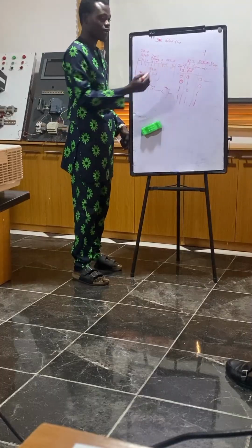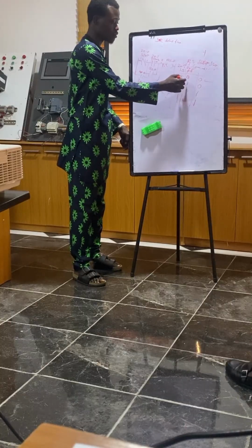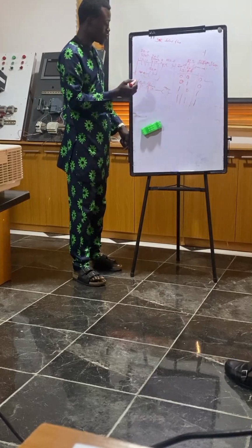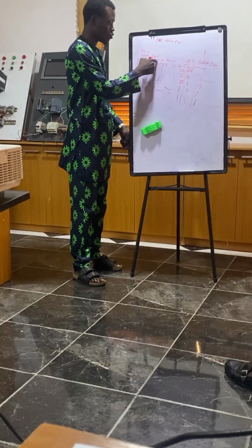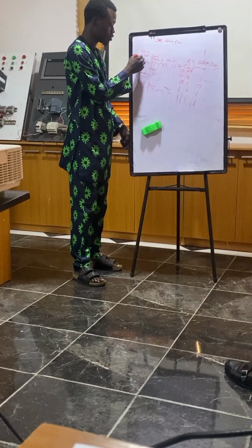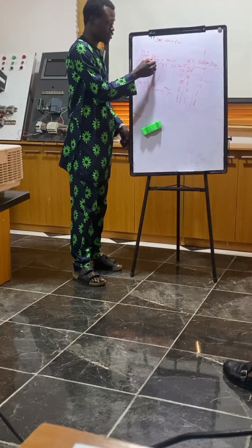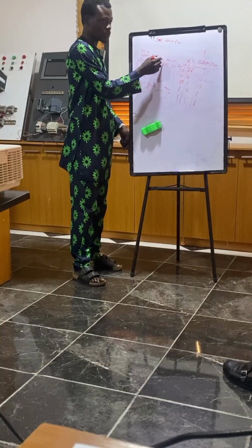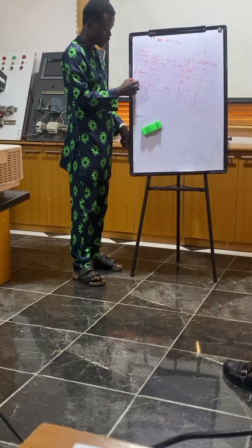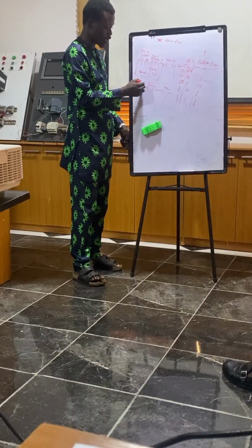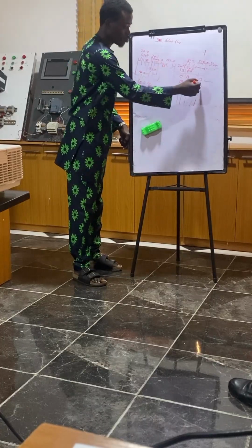The next one, we want to consider the set bit and the reset bit, where the set bit is not pressed, but the reset bit is pressed. So which is the set bit? The set bit is the start. Okay, it is not pressed, so you still have 0. And then the stop bit is pressed, you have 1, so this gets inverted. So you have 0. But this is still 0 0, so you still have 0 at this particular point. For the stop, you have 1 here, you have 1 here. 1 and 0 does not agree, so there is still 0. It means at this point you still have 0.